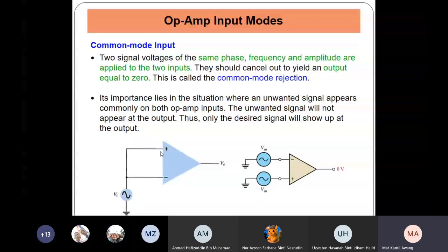So, it is better, sir? Basically, the higher the common mode rejection ratio is, the better the amplifier is. So it can reject the common signal and amplify the difference signal, which is not 0. Okay? Clear? Yes, sir.